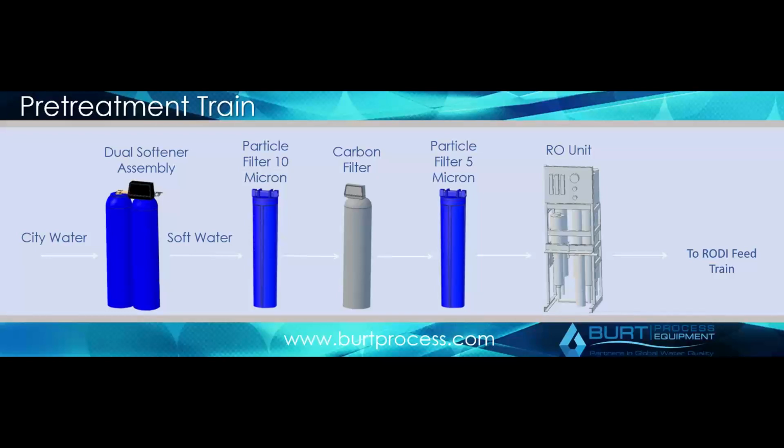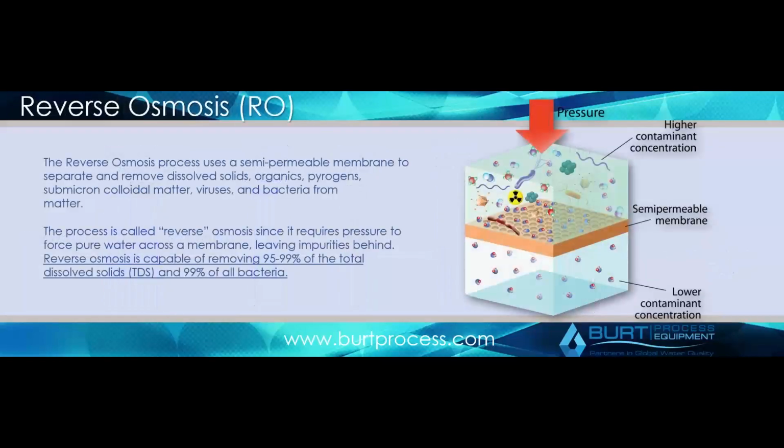And then obviously particulates as well. Based on the fineness of how an RO operates, you definitely don't want to be putting in anything with a lot of total suspended solids going into your actual system. And why is that the case? Because an RO membrane is a semi-permeable membrane designed to remove dissolved solids. A dissolved solid is any particle which is below 0.045 microns.